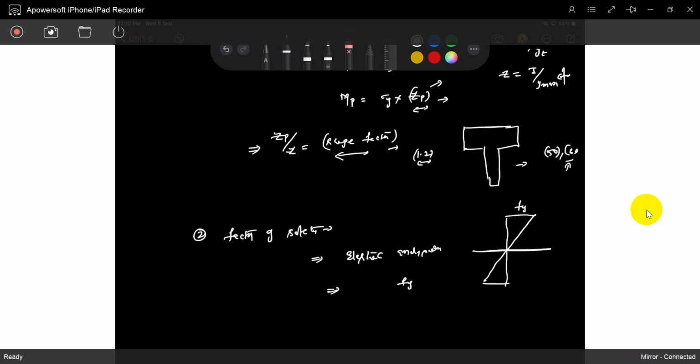You think that you will design like that, with the last fiber reaching Fy. But in reality, we won't, because we won't stretch the system up to the edge. We will give some relaxation. That means, if you applied a moment of 50 and it reaches Fy, okay, you can just take it, but we will design the system only for 40. If you can't understand, okay, I will say it again.